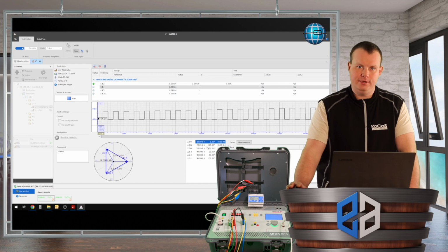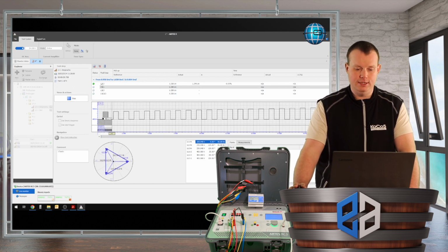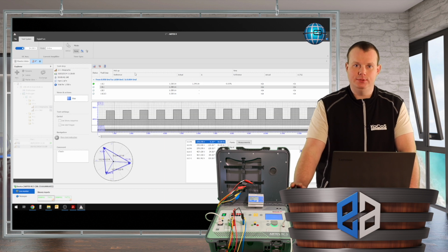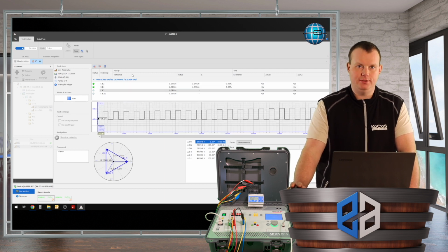After the trigger occurs, the test is stopped and the first ramp is automatically evaluated. We find the measured value and the difference, or the delta, to the reference value. Based on the allowed deviations which are saved in the IED, the test ramp is evaluated red or green. In this case it was successful, green.